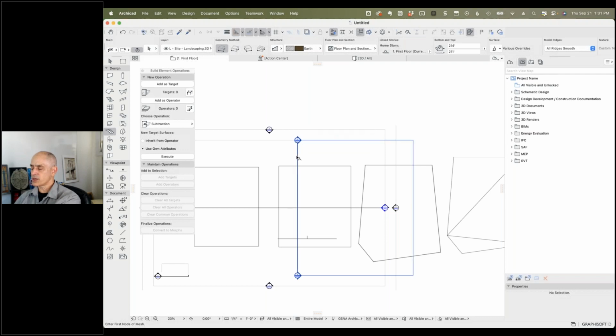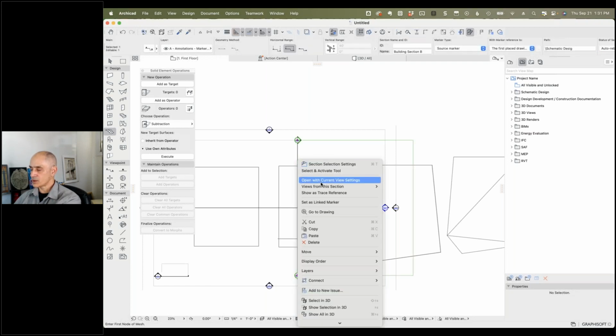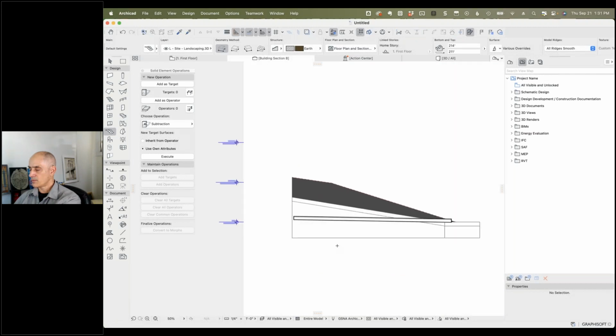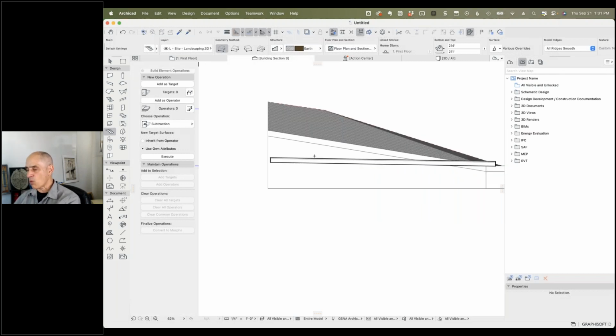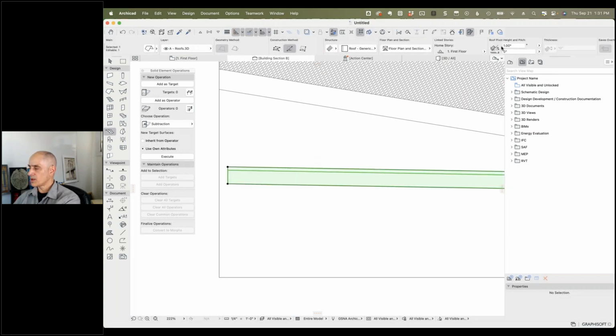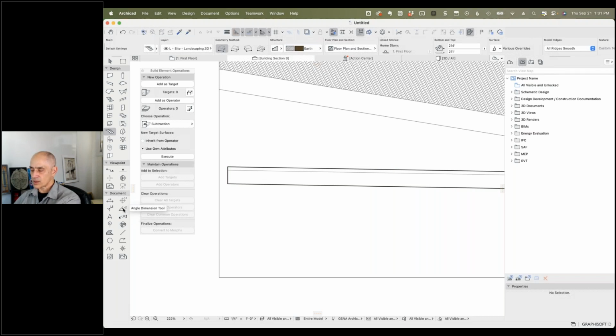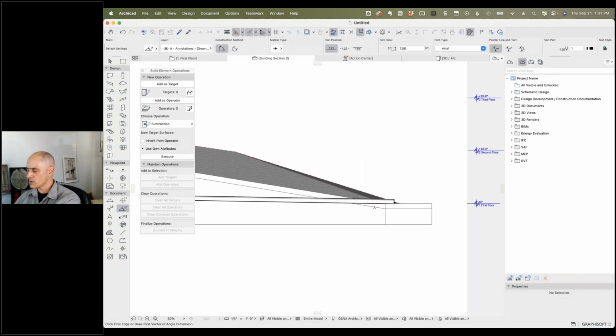Yeah. Here is a section right now, and I've just moved it to be in line with this roof. The roof I said is 1 degree was the last thing I had done. So if I say I want to open this section here, this is the roof that I'm cutting through here. What is that slope? So obviously if I select the roof, we can see 1 degree slope. If I want to annotate that 1 degree slope, then I could go, let's say, take the angle dimension tool. And let's see, I'm not quite sure what would be the most efficient way to do it.